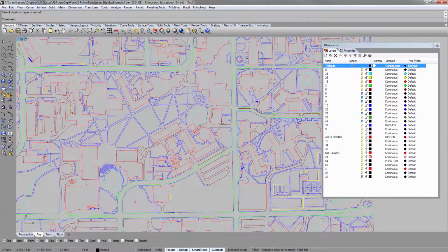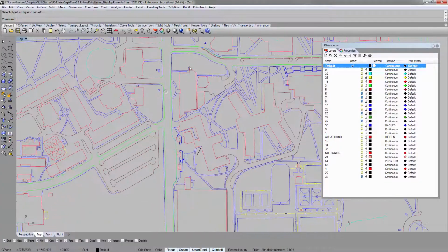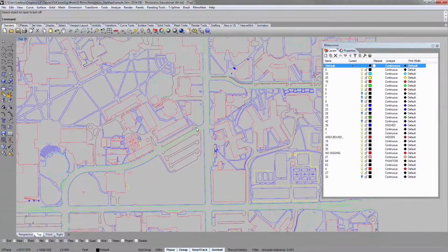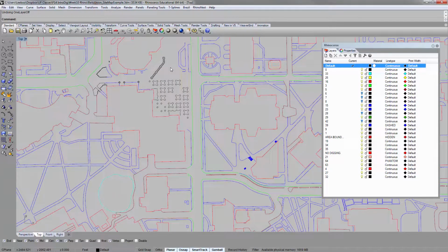And just look at the overall picture and say, well, is that too much? Am I hiding too much? And you can undo, just Control Z to bring that back if you accidentally turned something off, right? But if you right click, it will repeat not the undo command, but the command that you ran before the undo. So it's sort of handy. So let's just do that.